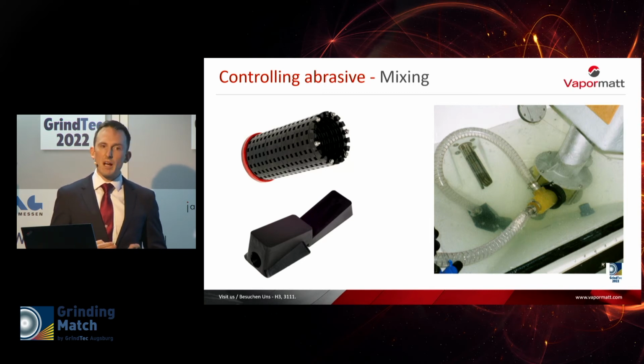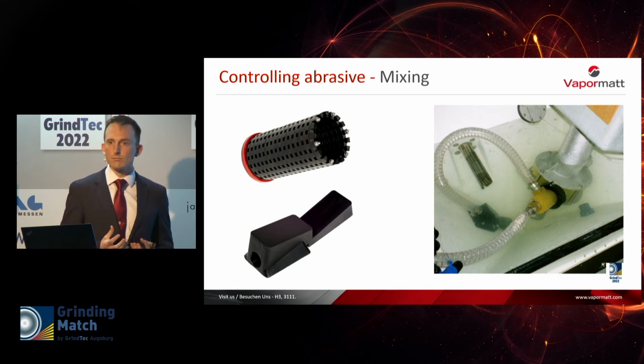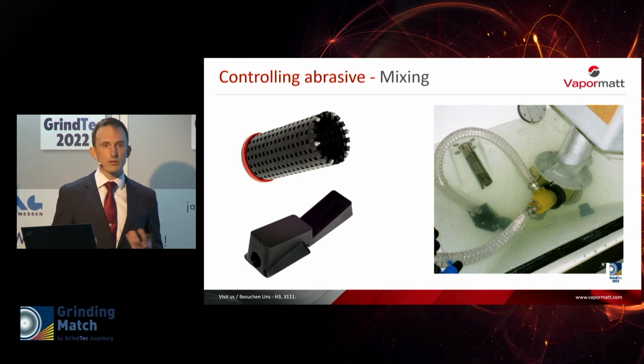Ideally, this pump will be mounted at 45 degrees, and the inlet will be no lower than the top of the abrasive once it has settled. This is to reduce blockages and to allow for quick pickup of the media after a shutdown or a weekend where the machine is not being used.